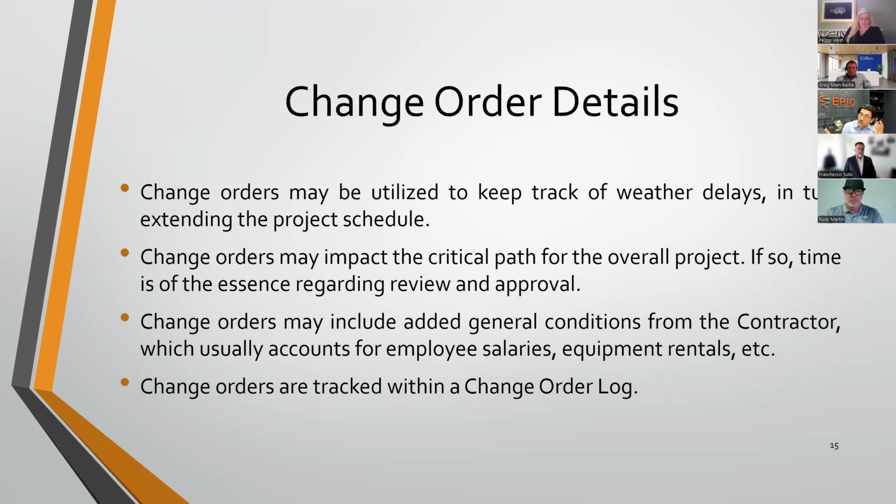Critical path, just a brief reminder, is if you have 3 steps, step 2 needs to happen before step 3. And if step 2 doesn't happen, and that's going to be the change order step, then you can never do step 3. Everybody will be waiting for that. And if the wait is too long, the contractor may say, okay, well, I need to utilize my staff on a different project where we do have things going on. I'm demobilizing, which would be the worst case scenario, because that means that the mobilization item that you have on your bid form and on your schedule of values is going to get triggered again when they come back.